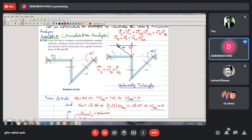And I get that AB means what? This is the relative velocity. I mean to say this velocity. Now this relative velocity equation magnitude is definitely equal to the length of this member AB, which happens to be equal to R, multiplied by omega AB. So this must be equal to omega into R. So definitely it gives me omega AB is equal to omega. So I find that if this is omega, then the connecting rod also has the same angular velocity, that is omega. Okay, that is one thing.